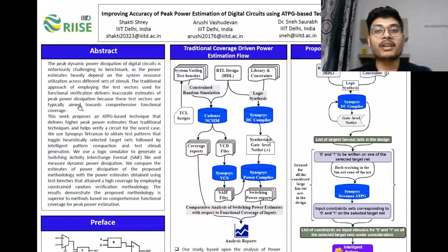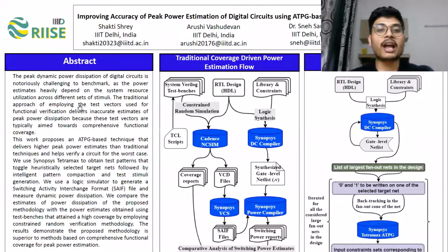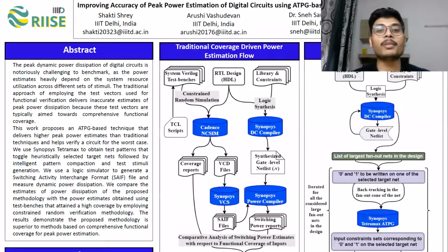While optimizing the circuit to achieve better performance, it is essential to realize that the increase in performance doesn't come for free, and rather we need to negotiate the power performance trade-off such that the system resource utilization fits in our power budget at the given operating conditions. Thus, it becomes necessary to know an accurate estimate of power consumption at the right time in the design cycle.